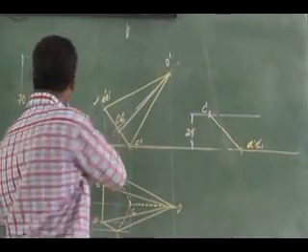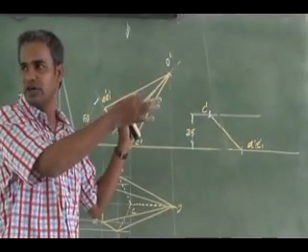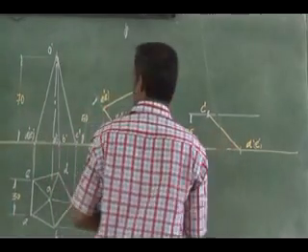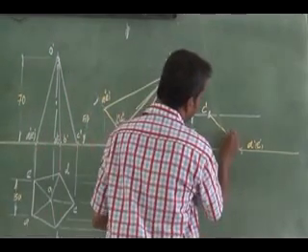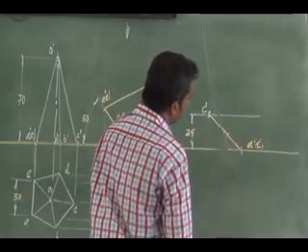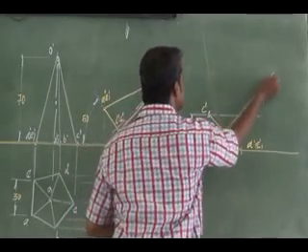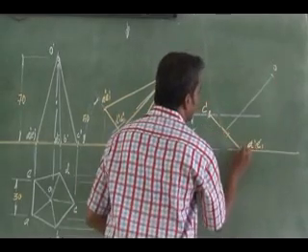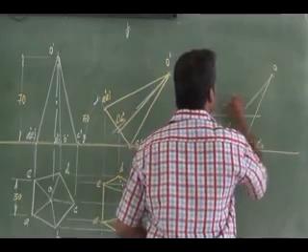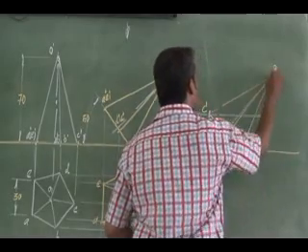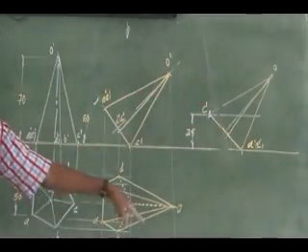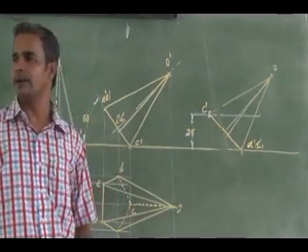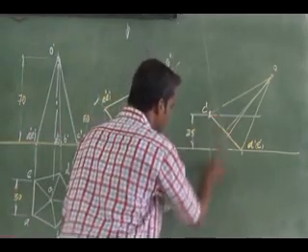Now what I can do is, just like that, you can redraw it to this orientation. The same front view can be redrawn to this orientation. See here, the other location I can mark. The axis location I can mark. I can draw an axis line. So you can mark the apex. You can connect. So again you have to proceed for the top view. The same top view will be a different top view here. How will it be? Just by projecting this.